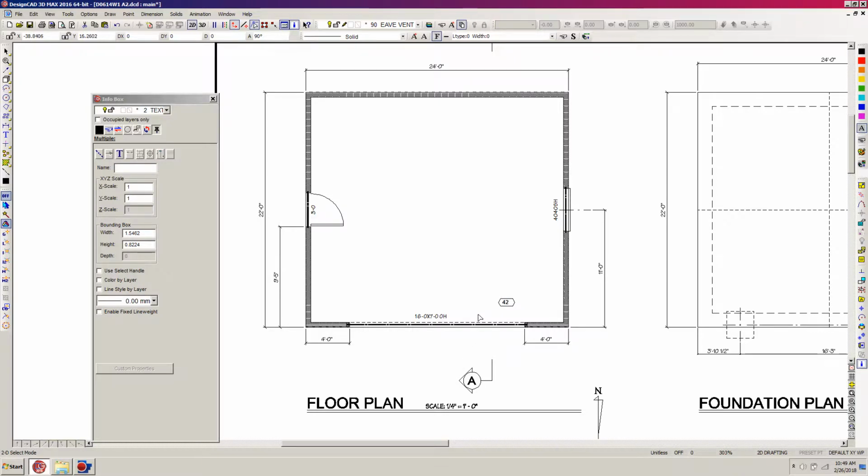I'm going to hit the arrow key, which again is Shift period or the greater than, same thing. And I'm still in orthogonal mode, which is fine. I'm going to right click to the pointy part of this box, come out a little ways to the left, and then I'm going to set one point, and then I'm going to hit H to go out of orthogonal mode. And I typically like to put my arrows at about 30 to 60 degrees, somewhere around in there. And I'm going to hit K at this fat garage door beam line, and then I'm hitting my scroll button, and that initiates the arrow command.